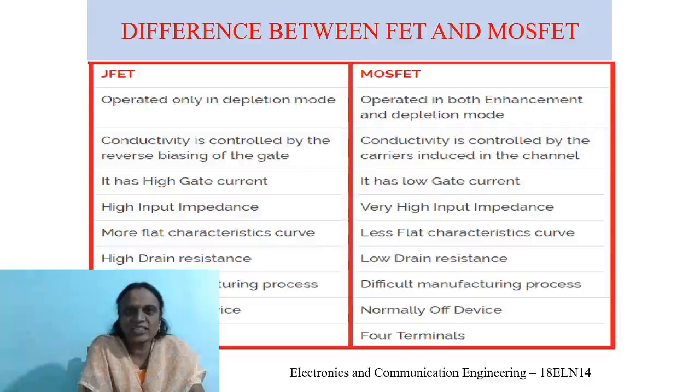When it acts as an open switch, it has a very high, ideally infinite, impedance. So the reverse bias of the gate input of the FET causes high input impedance. These are the two most important concepts: why the FET is sometimes called a square law device, and why the input impedance of the JFET is very high.